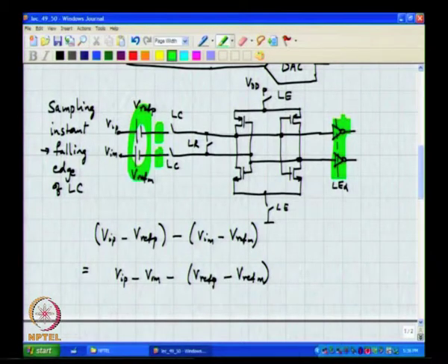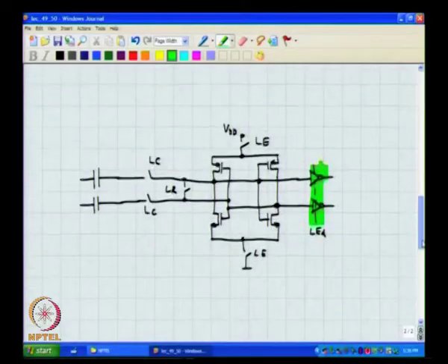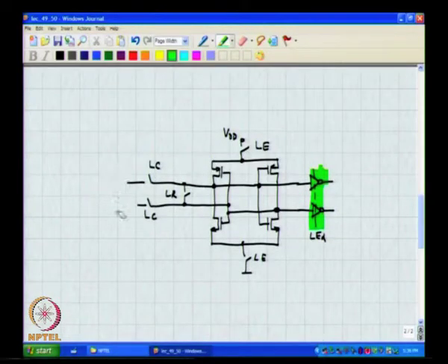You need these batteries only when LC is high, correct? When LC is not high, or when LC is low, the latch is regenerating. So, at that time these batteries are not needed, which means that is a good time to charge the capacitors, which will invariably lose charge otherwise because of all the switches connected to them. So, conceptually one could do this.